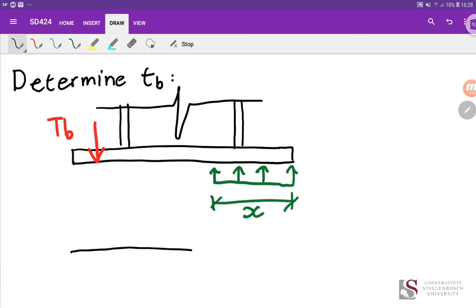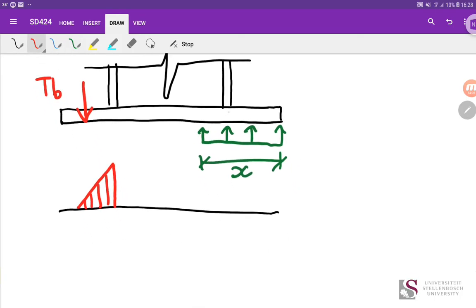But if we have a look at that diagram, and I plot what the bending moment diagram through the section looks like, we'll end up with something like this. So there's the bending moment on my tension side, and now I'm going to draw the bending moment diagram on the other side, but I'm going to plot it down. It will go right to the face, because it won't fail beyond the face, since the column coming down provides infinite stiffness. That gives us our resistance, because effectively we can model this as a cantilever sticking out with a uniform load sitting on it.